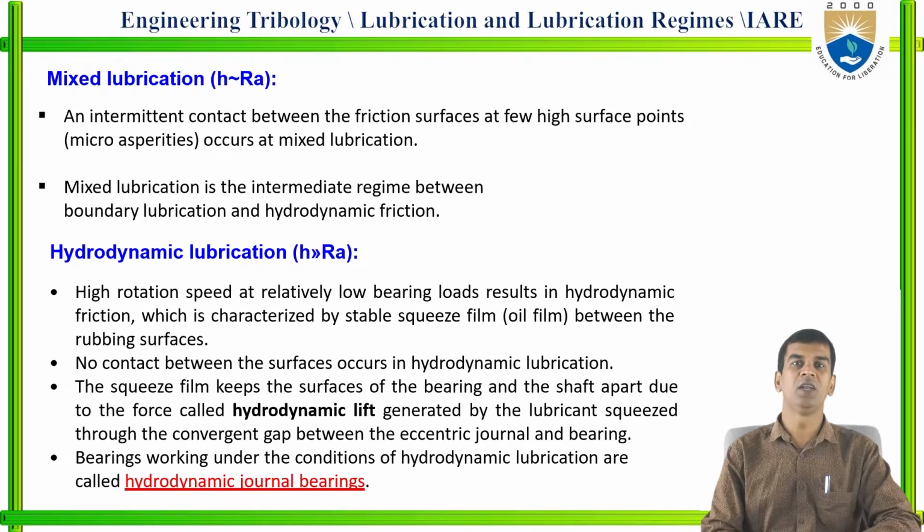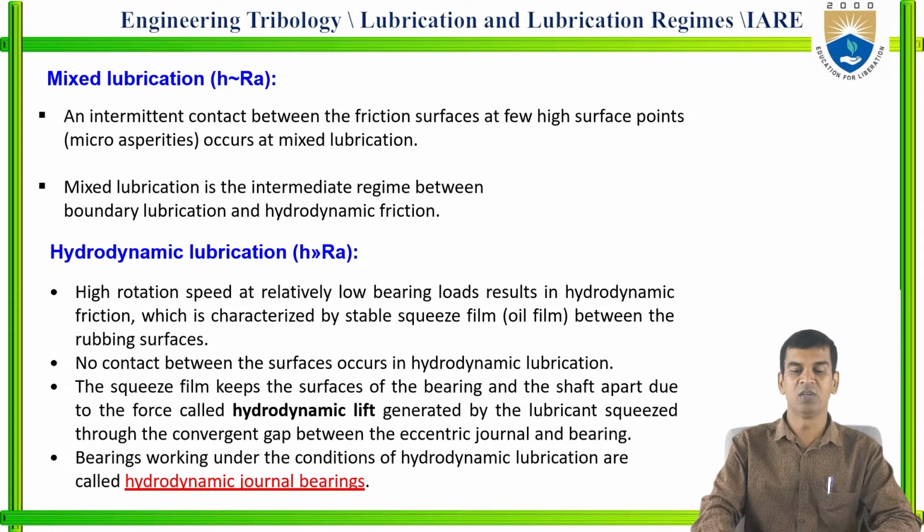Okay, that fluid plays a major role in keeping the surfaces apart. In that case, hydrodynamic lift will take place. Hydrodynamic lift is nothing but the lift force which separates the surfaces with the hydrodynamic lubricant. Bearings working under the conditions of hydrodynamic lubrication are called hydrodynamic journal bearings.